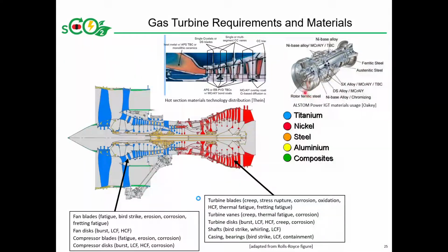The industrial gas turbines are, in general, of a heavier structural build with larger, beefier components, sections and combustors, usually using hydrodynamic oil lubricated bearings to support the shaft. More modern engines will make use of some of the aero engine technology that trickles down into the industrial engines, in terms of the directionally solidified and single crystal alloys, as well as the coatings on those materials and components.